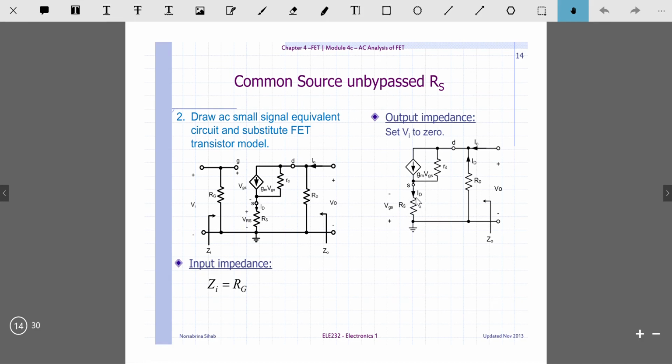A voltage will occur at the resistance RS. All resistances will have a voltage. So this voltage across RS is equal to the voltage VGS. Although the input is 0, still, due to the external voltage at the output, you will still have a value of VGS.